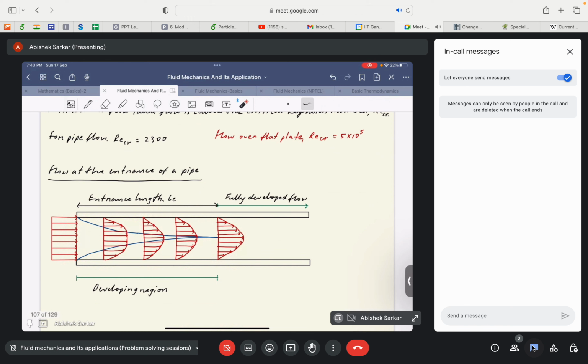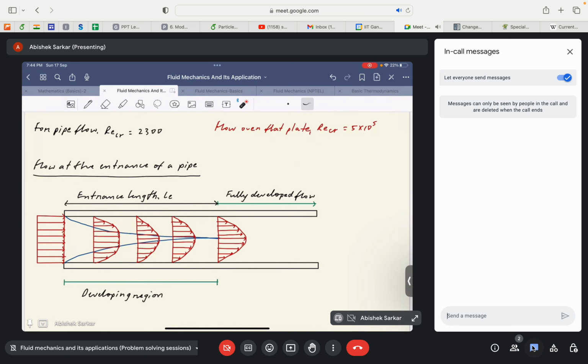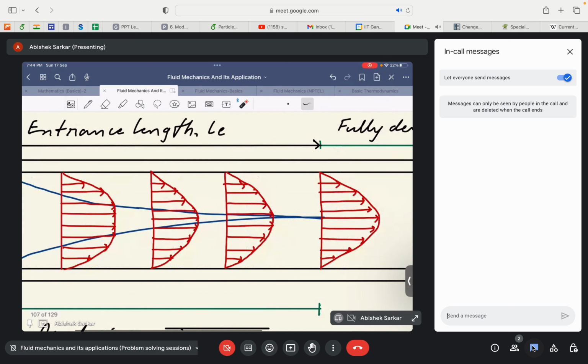Here you can clearly see the velocity gradients would be there up till the boundary layer, and after the boundary layer there is a straight line, which manifests the fact that the flow is inviscid in this region. Similarly, I will just zoom it a bit. In this region also the velocity profile should be completely straight. The viscous effects are only felt within the boundary layer, so outside the boundary layer it is completely straight.